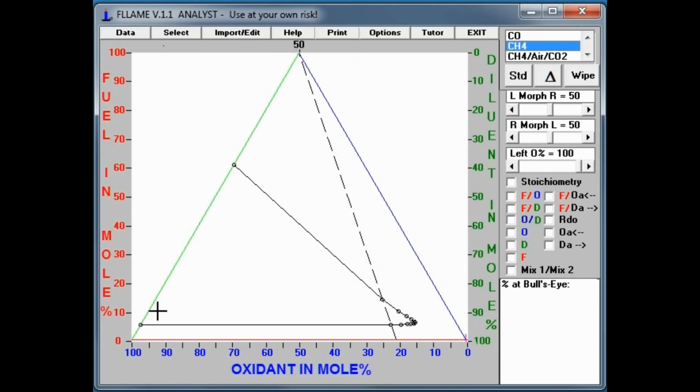Hence, one might not want to purge the methane with pure oxygen to avoid forming any of them. The broken line is between the pure air point and the pure methane point, and also passes through the fire region. Hence, it is also not a good purge gas prospect.